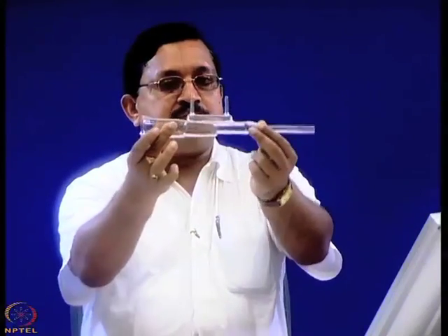I know. Actually, what happens? You see that a gas mixture passes through this chamber. There is a volume inside, and the susceptor is made in such a way that it is slanting. That means, as you go from left to right, that is from inlet to outlet, the volume decreases, the height above the susceptor decreases. You see that the temperature of the upper layer gas is less compared to the lower layer.